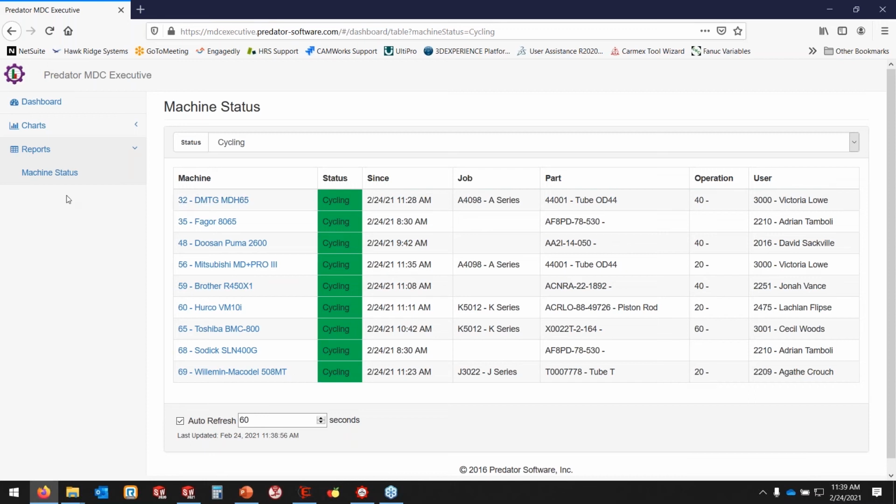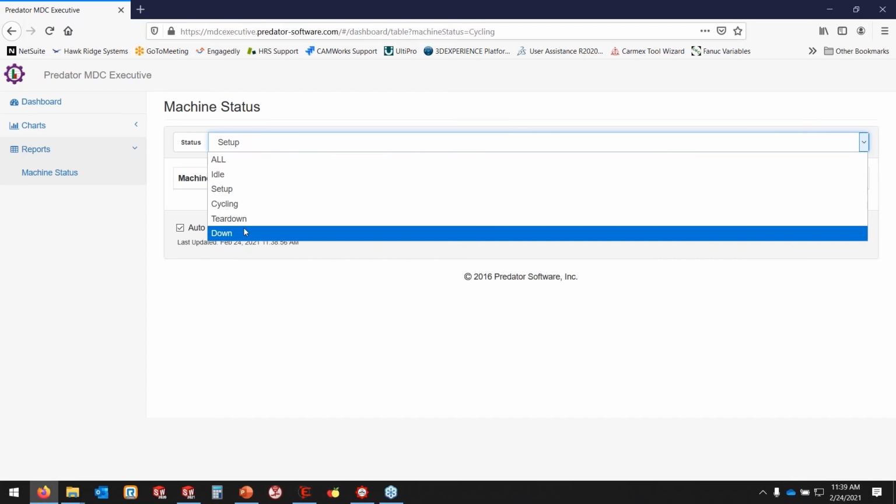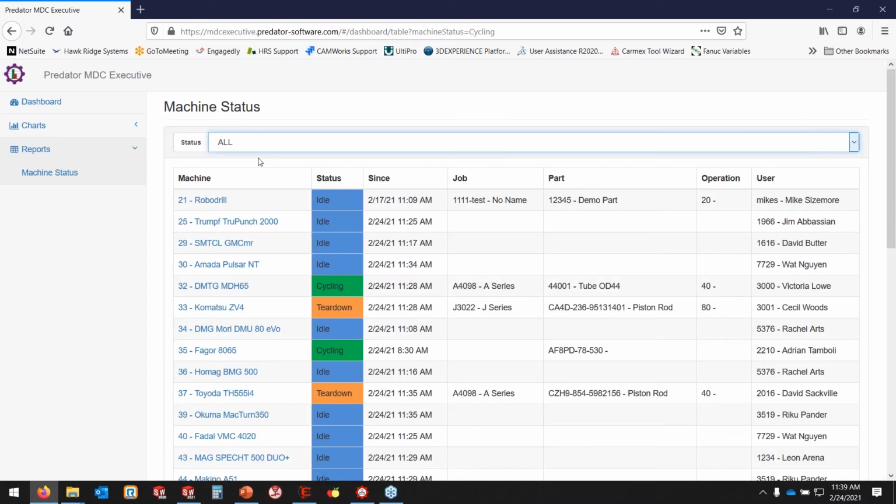This will work really good because I actually thought that we were going to be done with the UMC 500 yesterday. And then, when you did the design work, you figured out that it wouldn't fit anyways. I was going to try to put this job on there, and you said we had to run the 750 because you caught that collision in the simulator because of the height of the head.